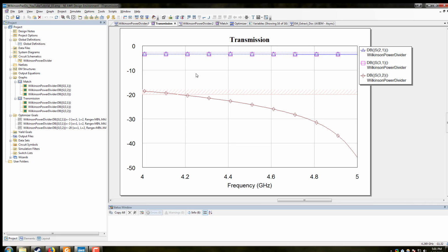So today you learned about why we do the EM simulation. This is in general. This is not just for AWR. Why we do the EM simulation, why it's important. The method of extractions, how AWR makes it incredibly easy for us to do EM simulation, specifically 2D, two-dimensional simulation. The fact that this enables us to do what we would call a 2.5D simulation. It is a hybrid between EM and circuit. How the EM simulation is set up in terms of meshing and the frequency sweep, and how we set up the extract block so that it properly extracts things.